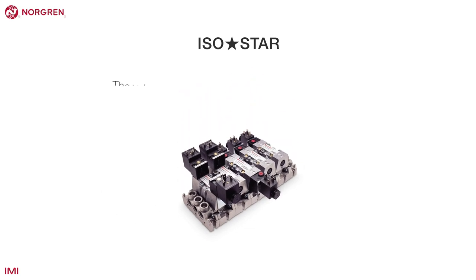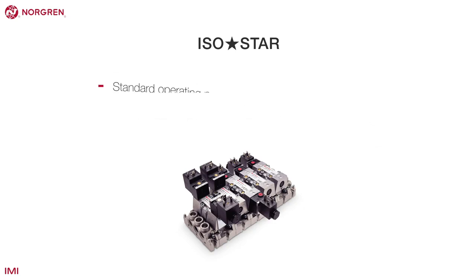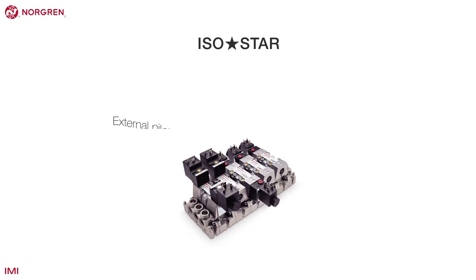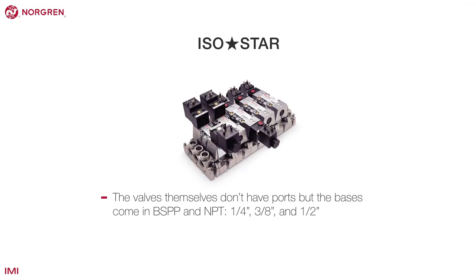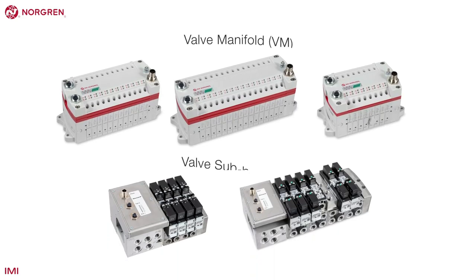The valve has a glandless design offering a very long life with fast, accurate, repeatable switching time through its lifetime. Its standard operating pressure is up to 10 bar or 145 psi, but the external pilot or higher power solenoid versions are capable of operating with a pressure of up to 16 bar or 232 psi. The valves themselves don't have ports, but the bases come in BSPP or NPT, 1/4 inch, 3/8 of an inch, and 1/2 inch sizes.